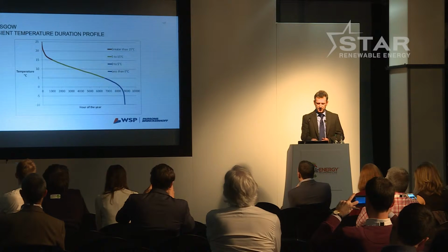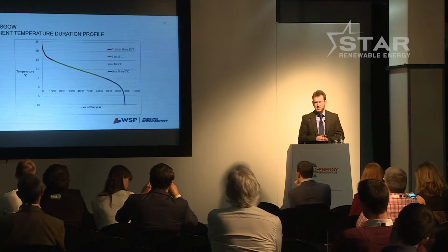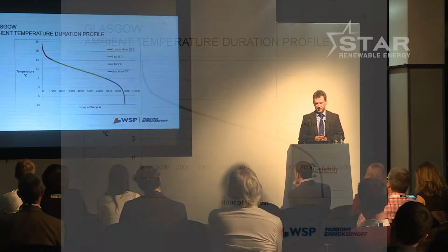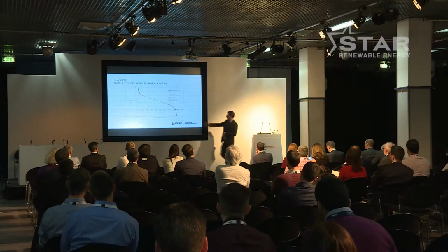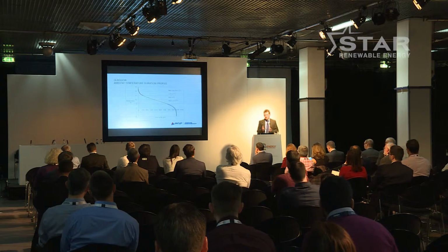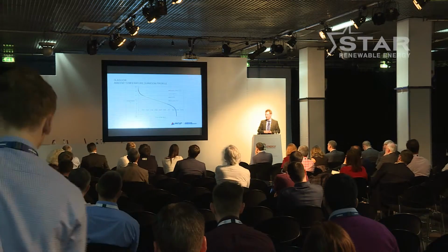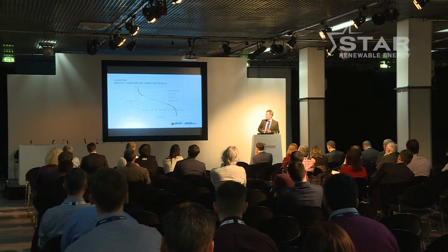When you're doing heating design, the focus is usually on designing for the design day, which in Glasgow is defined as a temperature of minus 3.9 degrees. That's right down at this end of the graph, and you can see that the heating demand through the year is any time the ambient temperature is less than 15, and most of the time it's between 15 and about 5 degrees.